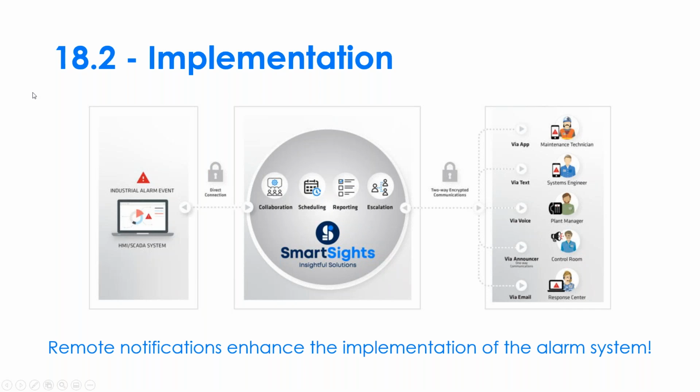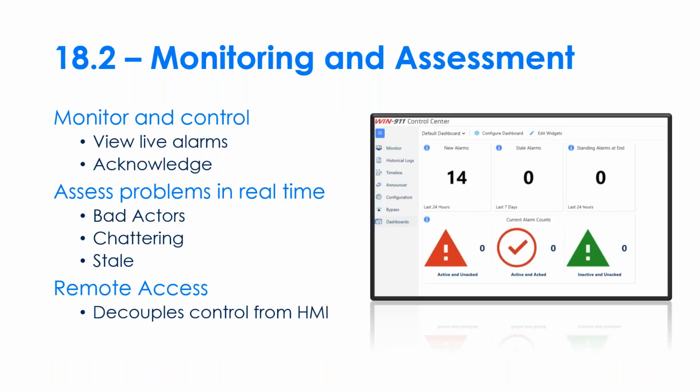Right? What conditions do we want to trigger remote notifications on? Who do they get delivered to? What method, and so on and so forth. Now, we also get involved in the monitoring and assessment phase, or can be involved in that phase, right? Because we're monitoring the alarm system, we're capturing key metrics about it to help people understand it. So think about the HMI alarm screen on your in-plant HMI. It tells you what alarms are happening.